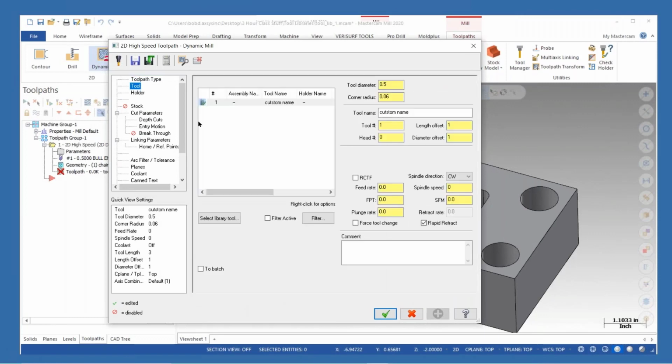Say okay to that. I'm going to go into my tool, and there's my tool. My speeds and feeds are the speeds and feeds that are defined in that tool. They're incorrect. So what happens a lot of times is all of the speeds and feeds in our tool libraries are incorrect. We need to go in and set them. So I need to come in here and manually take that 15 or 10 seconds, whatever it takes, and put all of my information in.